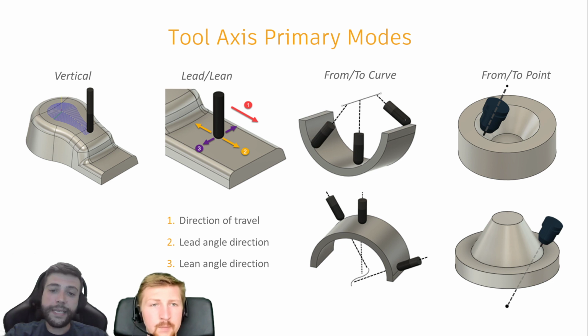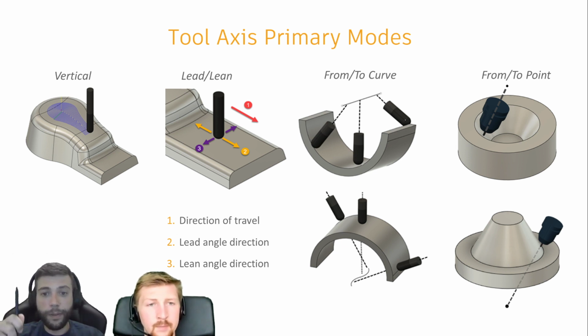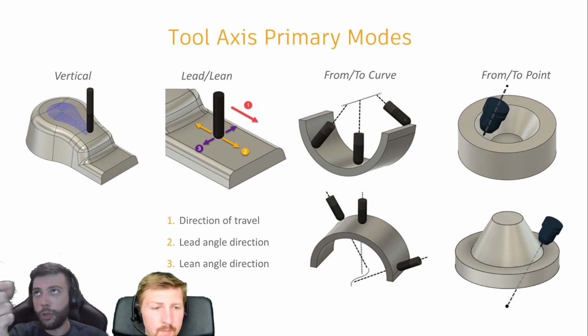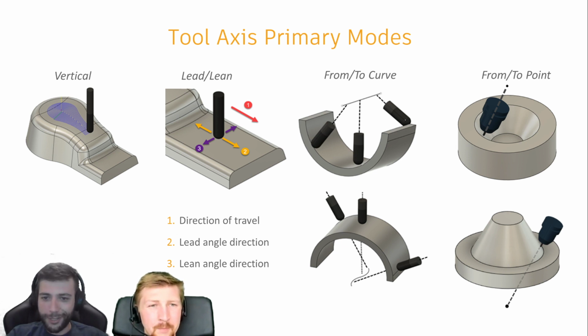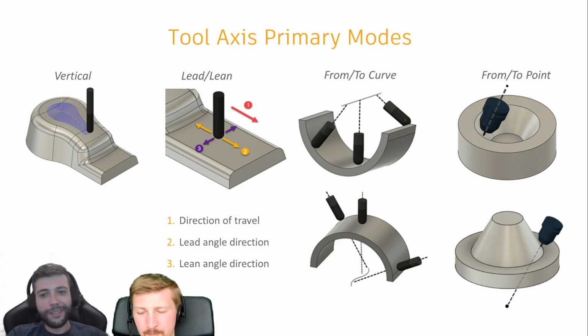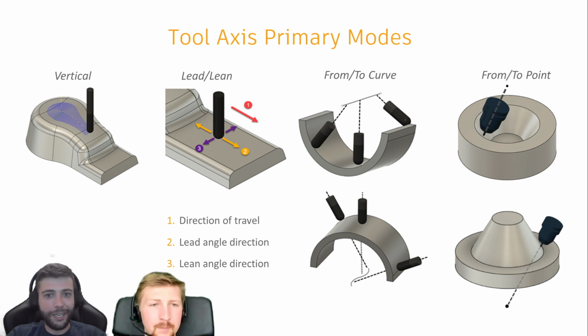So you can basically tell the software, start the toolpath, always keeping in mind that I want you to stay 5 or 10 degrees tilted, let's say, in the direction of cut. Why would you do that? You would do it not to cut with the center tip of the bottom of your ball nose tool, for example, your bull nose tool, your tip radius tool. You never want to cut with the bottom, really, unless you're machining something that's flat in one case, or unless you really want to.